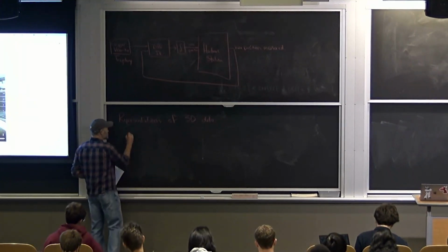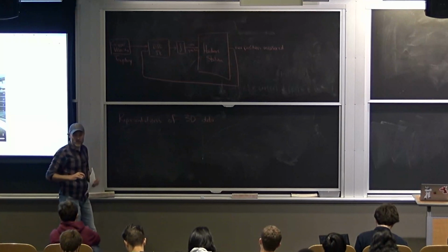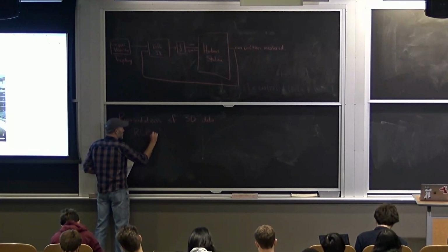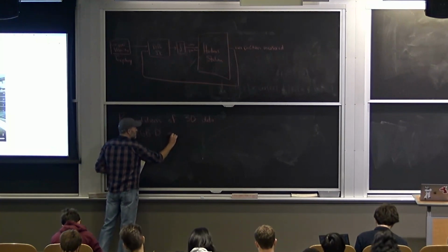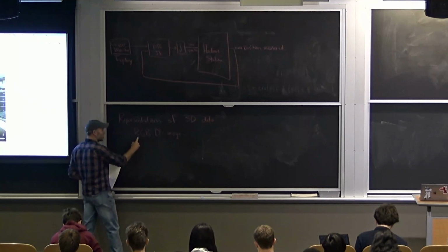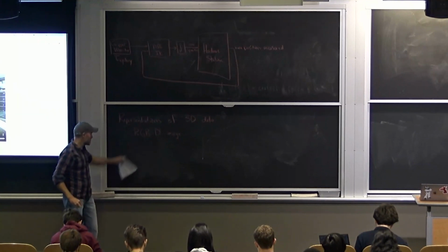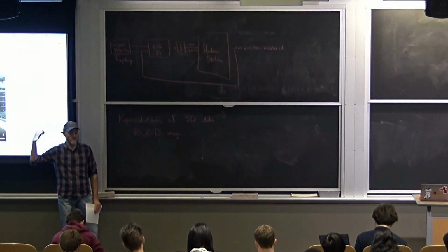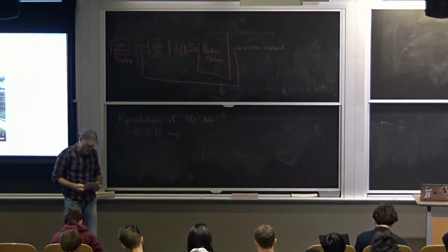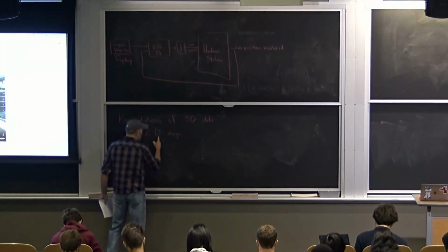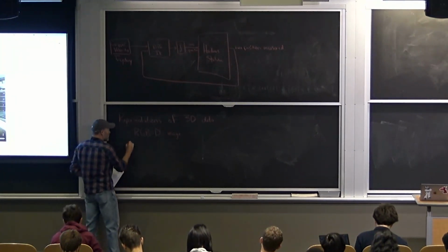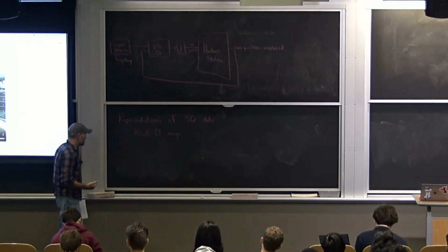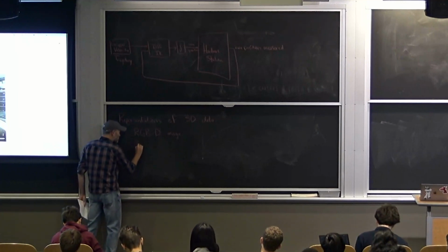So the image that you get directly out of a depth camera that has RGB, you think of that as an RGB plus D image. So it would have 4 channels. The first 3 are color values. The last one is just the depth at every pixel. That's kind of the output of these cameras by default. So that's 1 depth per pixel, right? We're going to take those RGB-D images, which is a perfectly good representation, and convert them into colored point clouds.